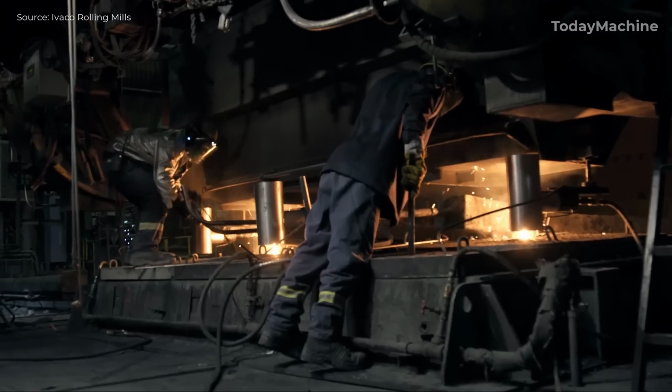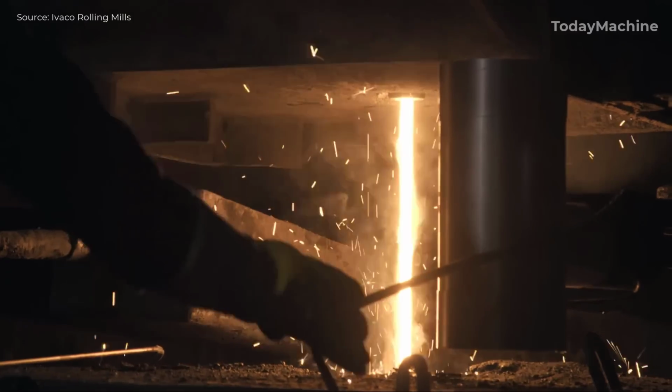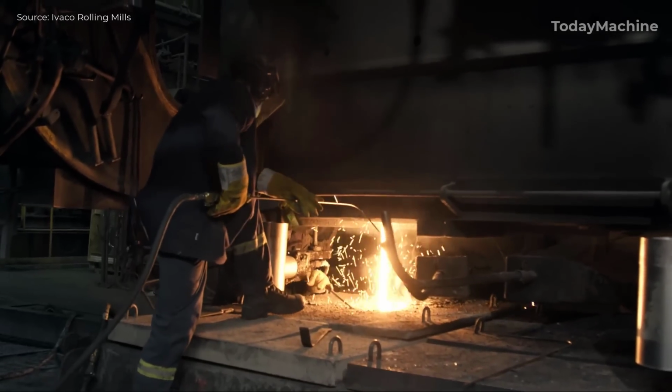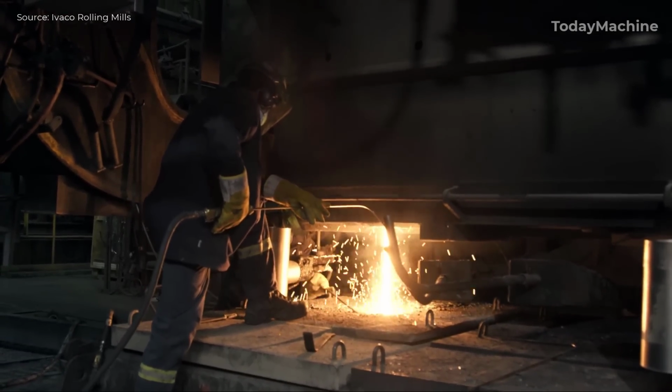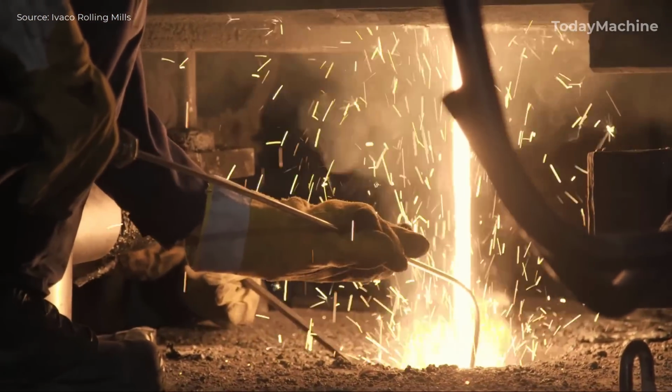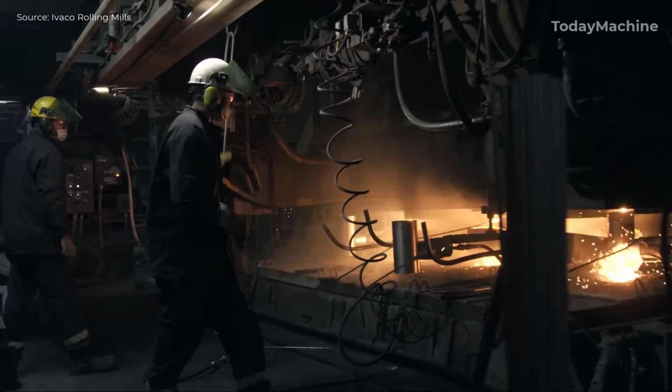During this process, additional alloys are added, and the molten steel is stirred with inert gas to ensure homogeneity. The LMF allows precise control over the steel's temperature and chemical composition, which is critical for producing high-quality billets and wire rods.